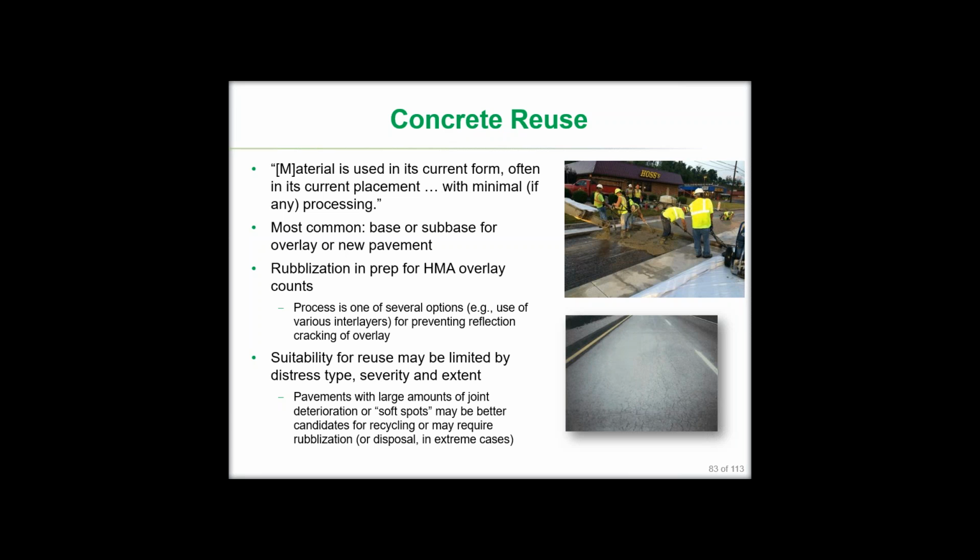But obviously any kind of a pavement that has lots of joint deterioration in particular, where you're going to have a non-uniform support condition result from the deterioration that's present, or some soft spots. Maybe you've had some blow-ups and things that have taken place and they've been replaced by repairs or temporary repair materials or whatever, might limit the ability to reuse that pavement, at least without doing a bit of work on it first, kind of some restoration work and activity.